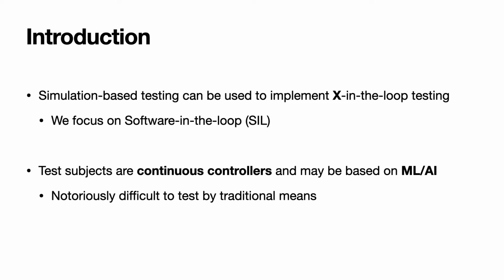Simulation-based testing can be used to implement X-in-the-loop testing. X-in-the-loop testing can be software in the loop, model in the loop, hardware in the loop. There is nothing preventing you from using this setup, this simulator, to test models and hardware. But what we usually do is use it for testing software. So in this tutorial, we'll focus on software-in-the-loop testing. We are going to test the software controlling the car, but not its deployment inside a hardware component.